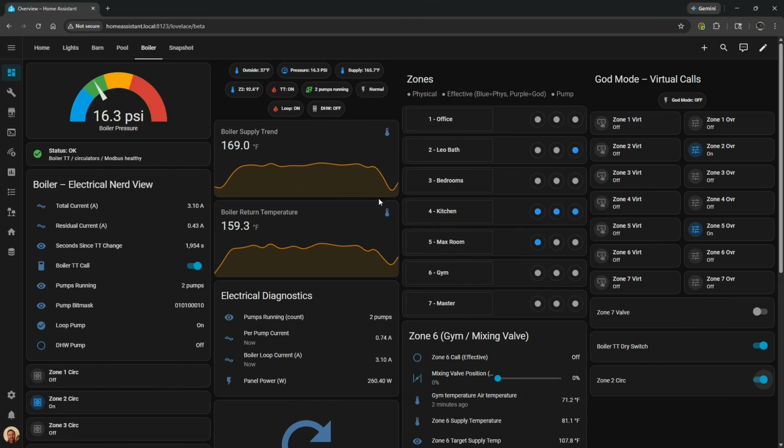So I've written logic so that, as long as zone 2 is running, that circulator just runs all the time, regardless of whether or not the boiler's calling for heat. But at some point, if it gets pretty warm and no one else in the house is asking for heat, the boiler supply water might drop below the 100 degree temp. And I think I have it at 120.